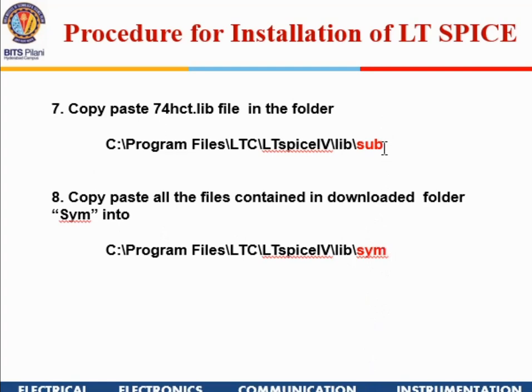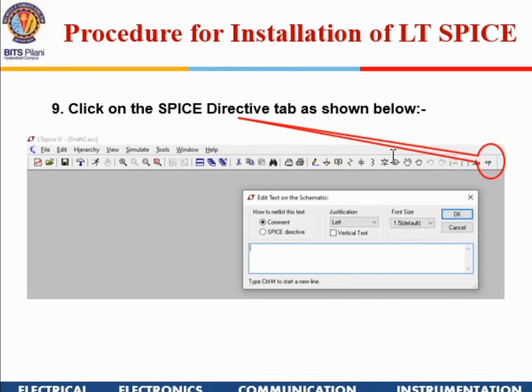Similarly, in the subfolder there will be so many other files also available. You just have to put these also into that subfolder. Once you have done that, you will have to shut down your LTSpice and reopen it once. Once you have done that, you have to now give the spice directive.